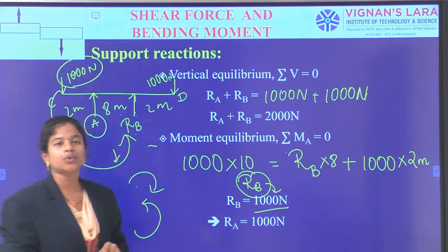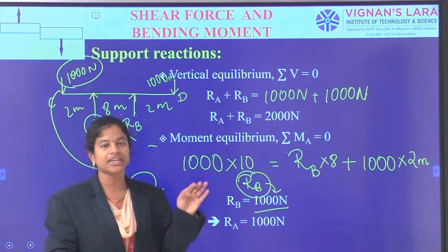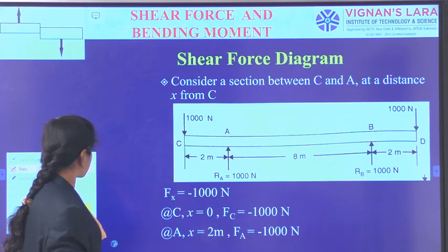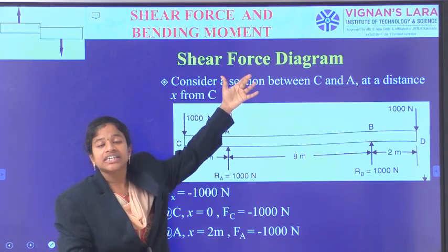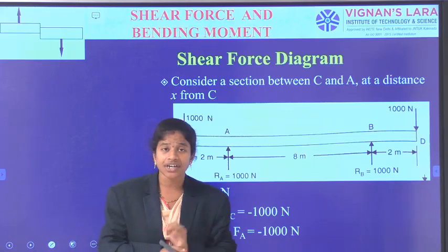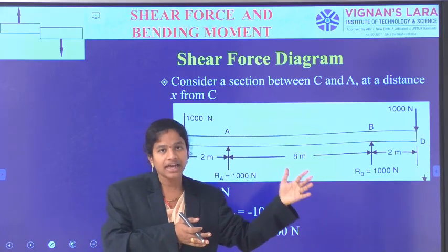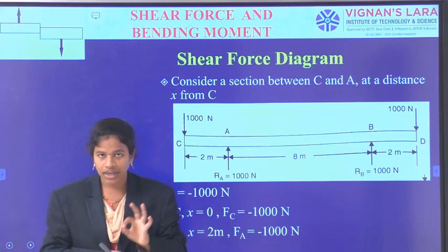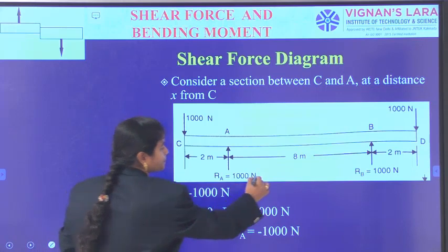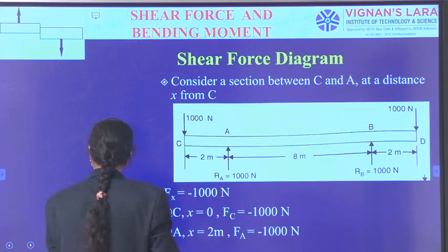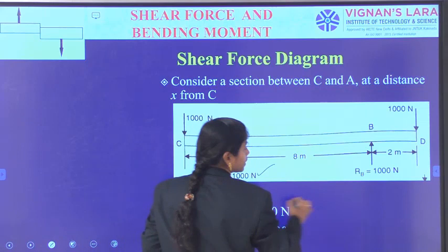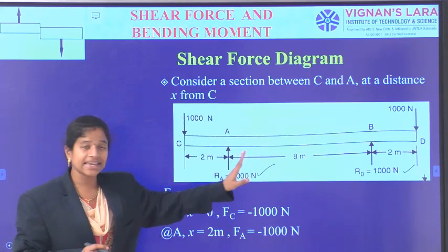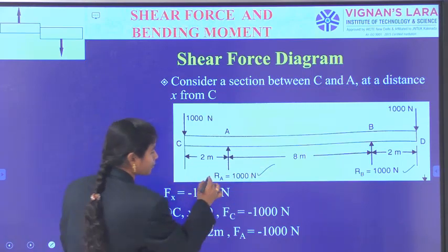Now, we are going into the calculation of the shear force and bending moments for each span. Okay. Firstly, considering the shear force diagram. As we have already mentioned, we need to take a section from the left side, and considering the load variation, we are going with different spans. Okay. Once I have calculated RA value and we have calculated RB value. Okay. Once we have calculated this RA and RB, no need of thinking about this RA.